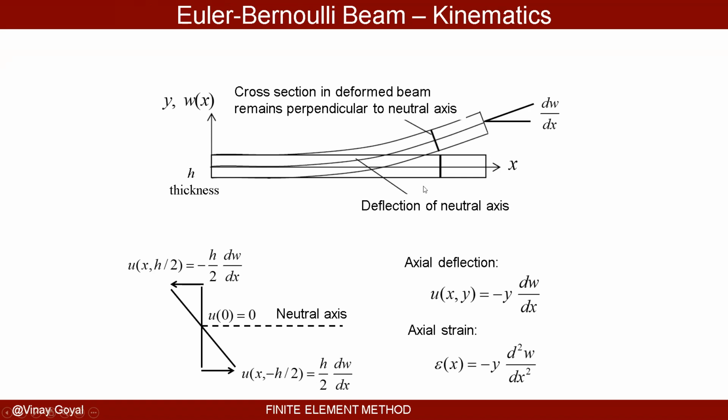You can see this point here moved to the left when this deformed. You can see that this point also deforms, but it moves to the right with respect to the neutral axis. So, blowing this up, this point moves to the left, this point moves to the right, relative to the neutral axis. And we can assume there's a linear approximation through the thickness.